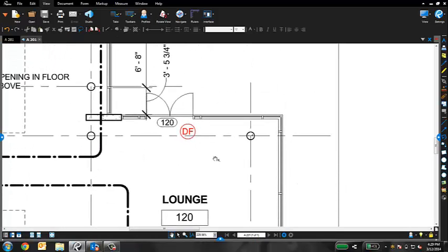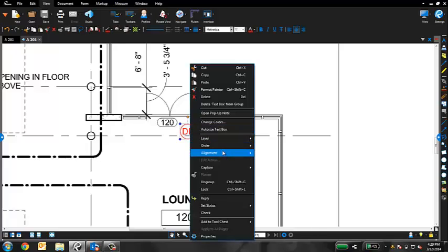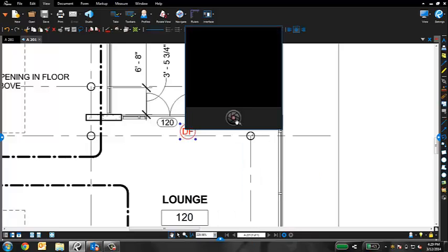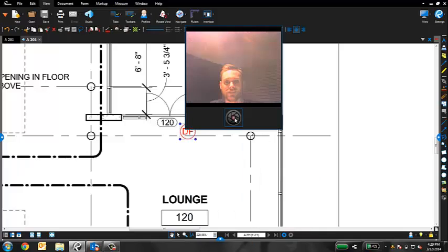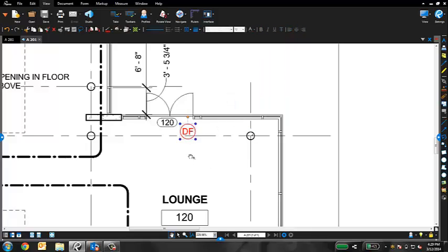And I don't have a lot of pictures of doors, but just as an example, I can show you how Capture is going to associate a variety of pictures with this particular markup. So if I click on this markup and right-click, bringing up my context menu, I can go to Capture, and I can take a picture of myself with the camera. We can throw that right in there into Capture. As you can see, this little camera icon just showed up. That's going to indicate that that's where my photographs are that are associated with this markup.